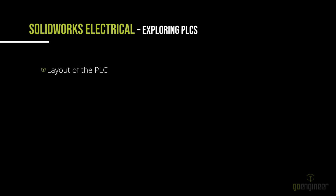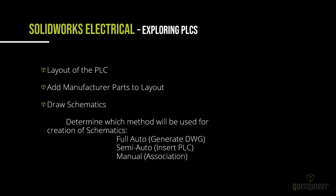Let's take a look then at possibly the layout of the PLCs. When we are looking at those PLC layouts, one of the next steps we will be doing is adding manufacturer's parts to that layout. From here, we will draw the schematics. There's a number of ways to draw these schematics. These are my terms: full auto, semi-auto, and manual. In the software, they're called Generate Drawing, Insert PLC, or the simple association, which you are probably used to with your current drawing schemes. So let's look at the layout of the PLCs.